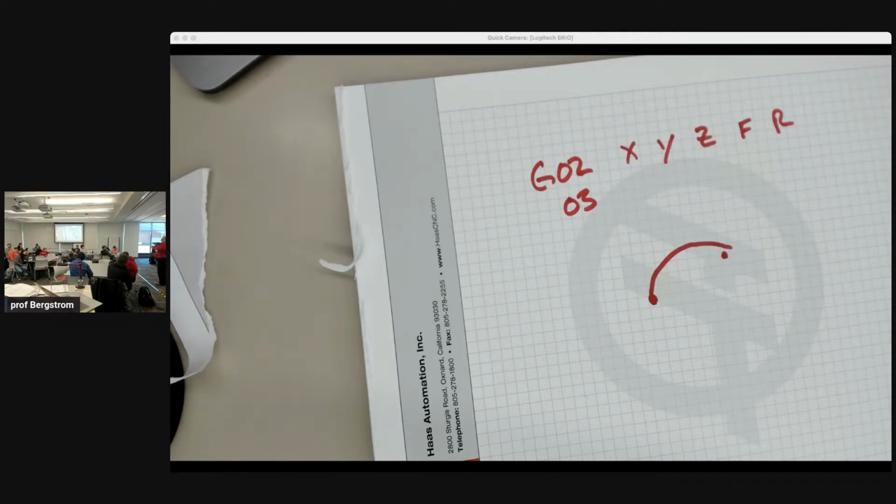We did all that, like the diagrams and stuff about how chips form. We were not making chips. We were forming the material. We were pushing the material out of the way with our 30 horsepower lathe, because the code that it gave us to start the spindle had it start spinning the spindle in the other direction. So we were just mushing metal around. It was a small part. Steel, though. Mushing the metal. The parts did not look good. That's why we kept iterating to try to figure out what the problem was. Turns out the spindle was spinning the wrong direction.